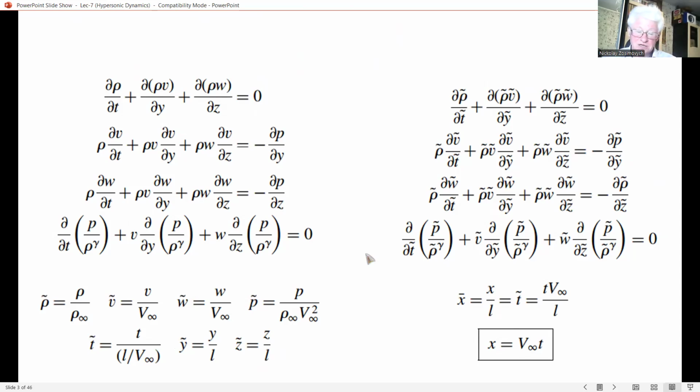Compare these two sets of equations. You should note that they have slightly different symbols, but they are an identical set of partial differential equations. On one hand, these equations are the hypersonic small disturbance equations, which govern the steady three-dimensional flow over a hypersonic slender body. On the other hand, these equations govern an unsteady two-dimensional flow.